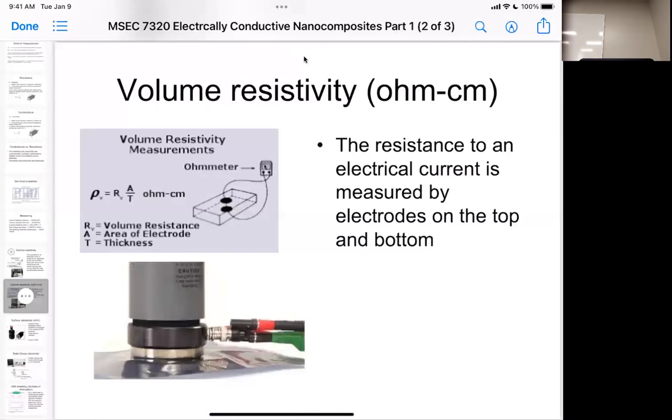But one thing I should mention is the surface electrical properties actually change with humidity. You can absorb something onto it, and that will change your surface resistivity. And that's another reason why the bulk or volume resistivity is actually a more constant number, because you're never going to get the entire volume of it blended with whatever is contaminating your system.